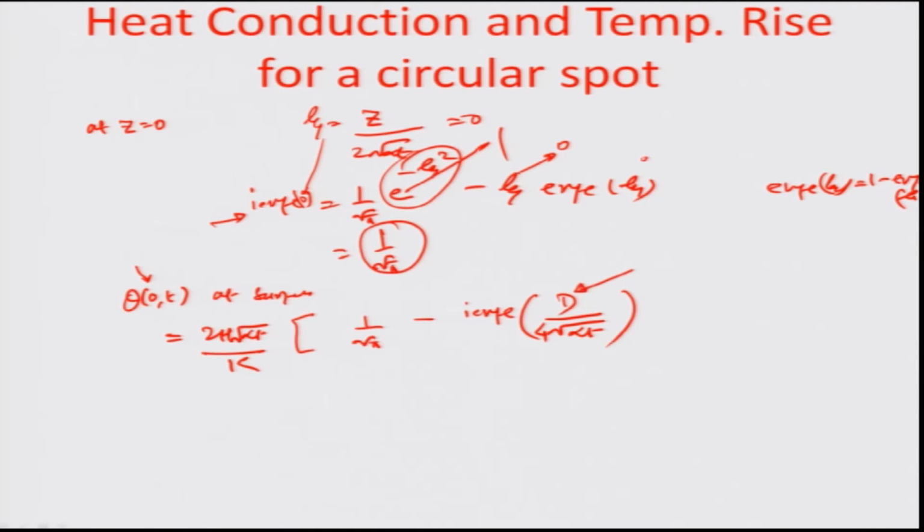So, at a certain beam diameter, let us say d equal to a 2 millimeter spot size, or 1 millimeter spot size, or even a few hundred micron spot size, for a certain alpha value, that is the thermal diffusivity value, the question here is what is going to be the time in which theta reaches theta m, through which you could get an indication of the machining time.